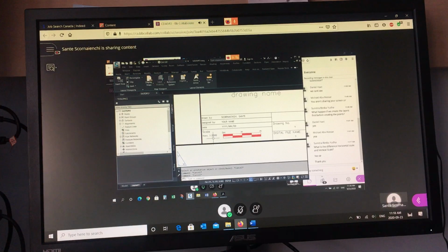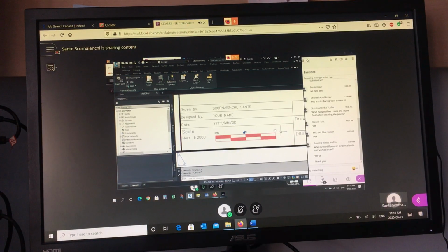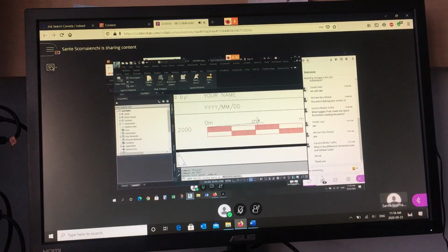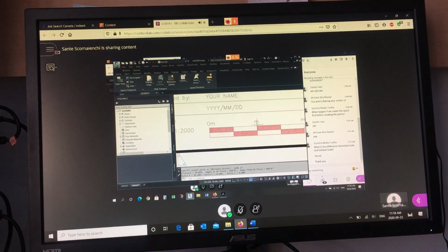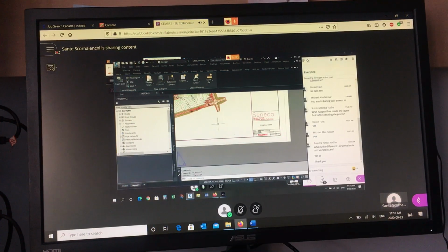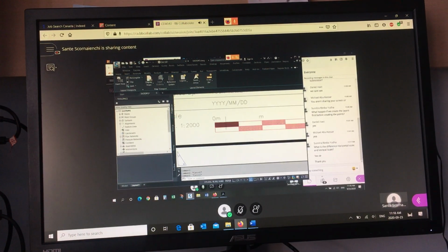So that's 2000. And then here you want to change the text on these 2 items. Okay, the distance from here all the way to here in paper space is 20 meters. What does this distance from here to here represent in this space? Remember, the scale is not exactly 1 to 1, it's half size. So you need to decide, is the distance from here to here, it can't be 20, it's got to be either half the distance or twice the distance.